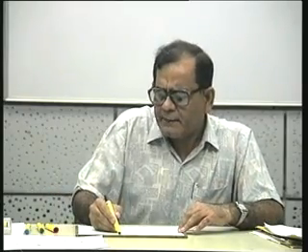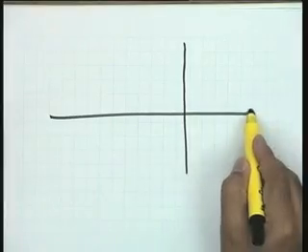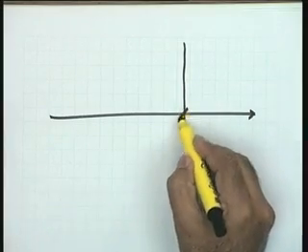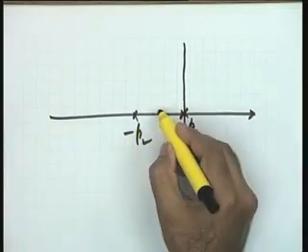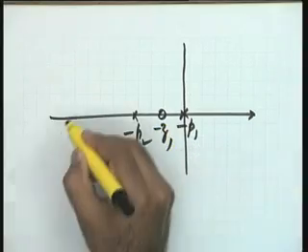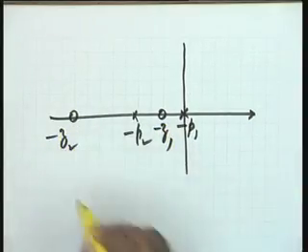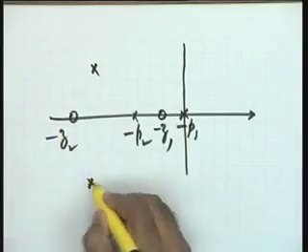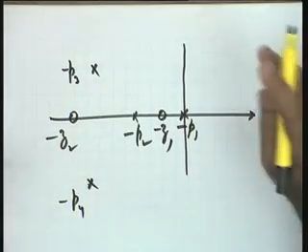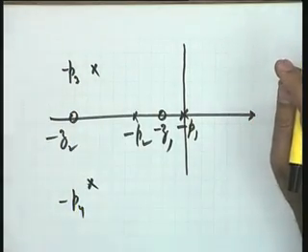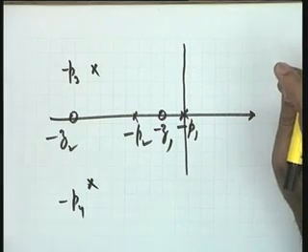The question now is this, that you scan the entire S plane so that the angle condition is satisfied. A brute force method, you can say, will be like this. Let us say this is your minus p1, this is minus p2, a value of minus z1 I am taking, another value of minus z2 I am taking. I could take two poles here also, minus p3, minus p4. These are the open loop poles and open loop zeros of the function F(s).